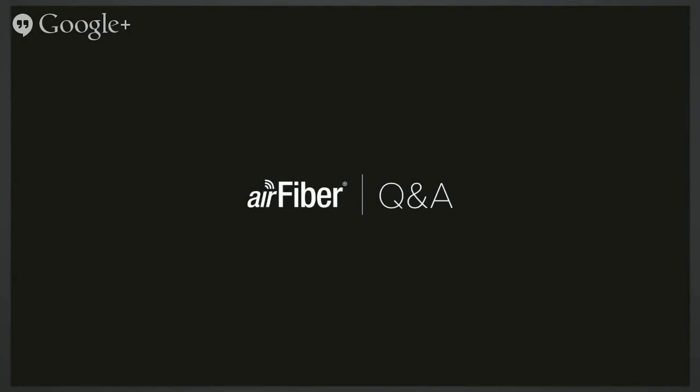You don't. So when you hear about these high MIMO rates, in the outdoor environment, you have to take some of that with a grain of salt because you just don't have tons and tons of reflections. 5 gigahertz and 24, even more so, are really not frequencies that tend to propagate around things. The reasons for that have to do with the wavelength. If you have a very long wavelength, say something running very low on frequency, around a gigahertz, then obstacles of a certain size won't affect the field. The field will go by, see that, rebuild on the far side of, say, a tree or a building and keep going.